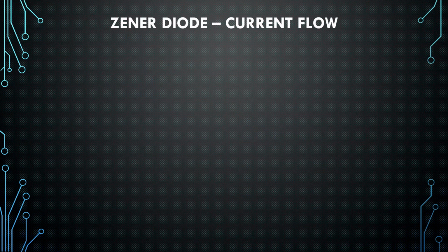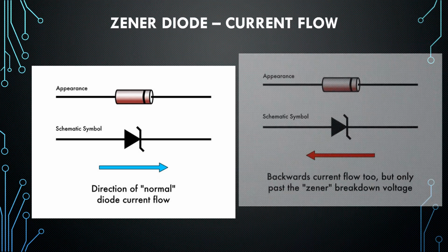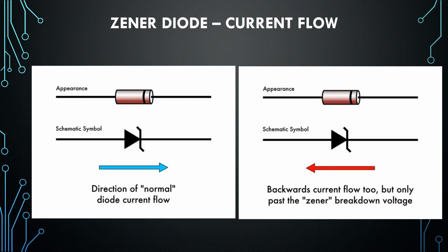What is a Zener diode? A Zener diode can be defined as a special kind of diode when we compare with other diodes. The flow of current in this diode will be in the forward direction or in the reverse direction. The Zener diode includes an individual and heavily doped PN junction which is intended to perform in the reverse bias direction when a particular voltage is reached.